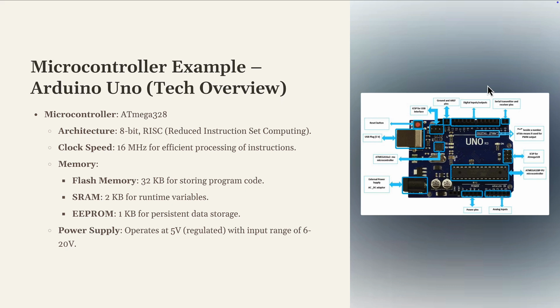Look, here we have digital input and output. All these inputs are for digital type of sensors or digital devices. If you have an analog device, you need to connect it here. Why? This device will provide an analog signal, but internally in the code, you will be able to process digital information. So you need to convert this signal from analog into digital. And this is why we should have special hardware here that is called analog to digital converter, ADC, that will convert the analog signal into a digital signal, and later on you can process the information in your code.